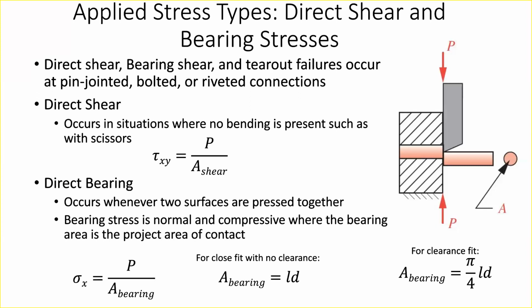If I'm able to do that, I can resist much higher loads than if I were loading my tubes in bending. So constraints are another super important aspect of part design that you recognize once you go through these exercises of looking at the solids. And there are equivalent considerations that you make for bearings or really any kind of interface between two parts. I won't go into too much detail, but the general gist of it is: recognize the patterns of loading that go on in your parts, recognize the constraints that result in those patterns of loading, and try to design those out so that your part is loaded as optimally as possible.